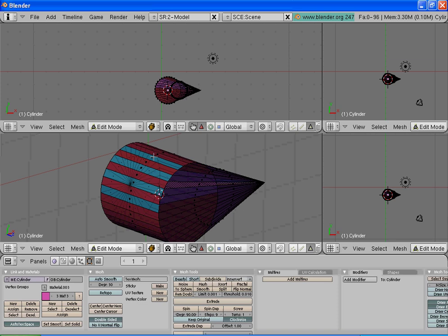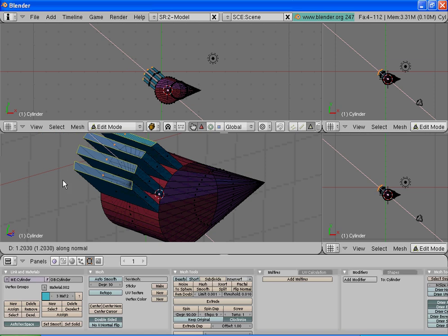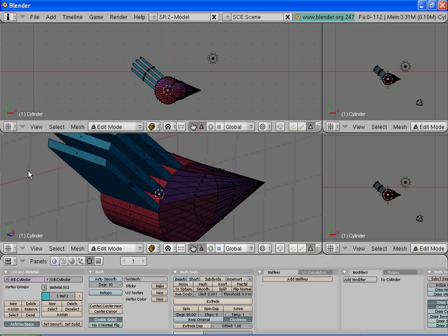For this next part, we're going to use these blue areas. I've colored them blue so you can clearly see what I'm doing. It's something called extruding, which is going to lift the faces out from the object. So I'm going to shift, right click, and hit the extrude button right here. I'm going to click over here again and extrude region, which is every highlighted surface on the object that I have decided I want to extrude. So region, and pull it up. A for deselect.